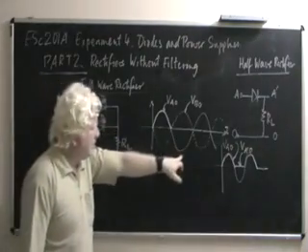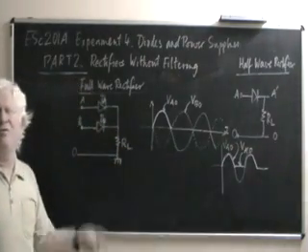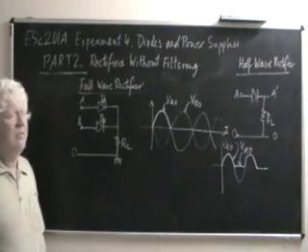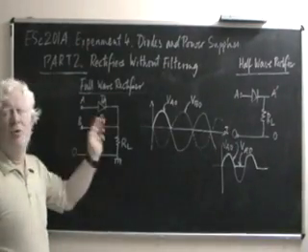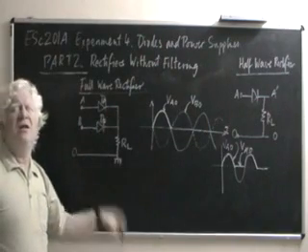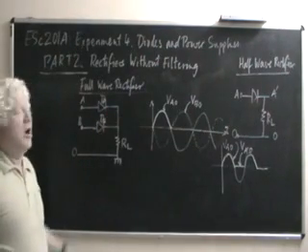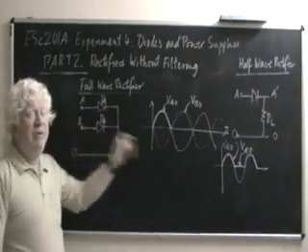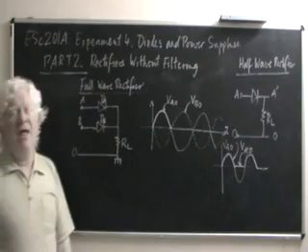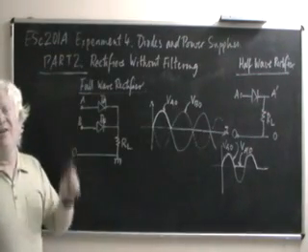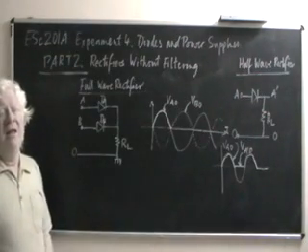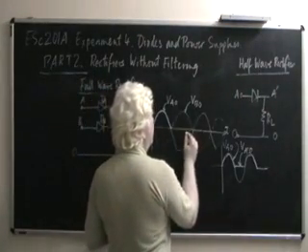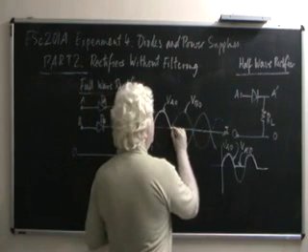In the second part of the cycle, the voltage of A is negative, so DA stops conducting, and so it is unable to contribute to the current in the resistance. However, at this time, the voltage of B goes positive with respect to O, and so DB starts conducting. And this conduction occurs for the second part of the cycle when A was negative but B was positive.